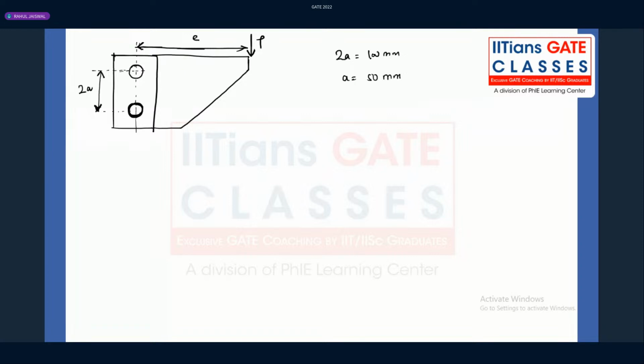Very first of all, tell me, if you just transfer the load to the center of gravity, for example, here, this is the center of gravity. If we transfer the load P here, I'm applying two loads, P like this, P like this. So this P and this P will basically what? What is the equivalent diagram? The equivalent diagram will look something like this. There is a P and there is some twisting moment, P into E. That is the equivalent diagram from the bracket to the particular rivets, right?